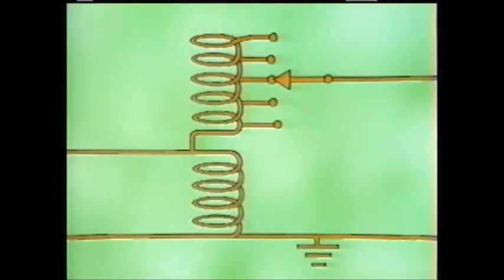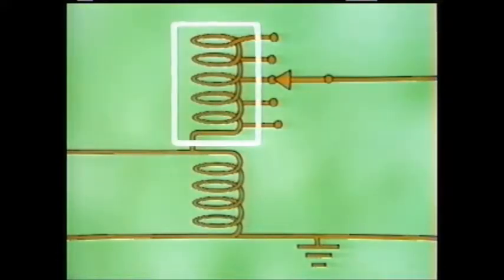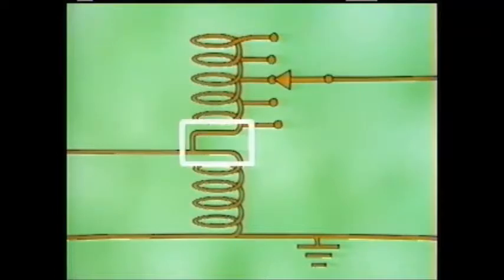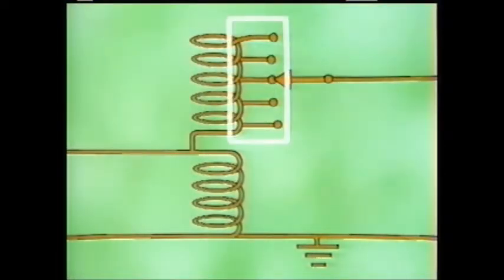This simplified diagram illustrates the basic electrical components found inside of a voltage regulator. They consist of a primary winding, which is wired in series to a secondary winding. The series connection causes the primary winding to also function as part of the secondary winding. A tap changing mechanism connects the voltage regulator to the distribution system through taps. On our simplified diagram, 5 taps are shown. In an actual voltage regulator, there may be 30 or more taps.